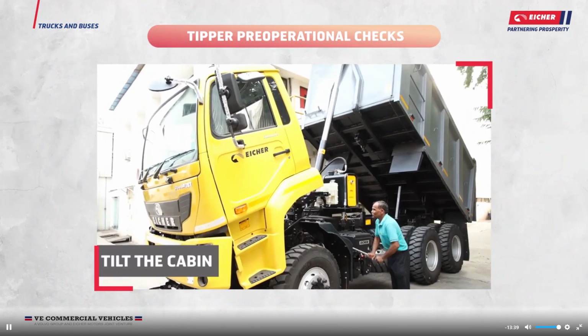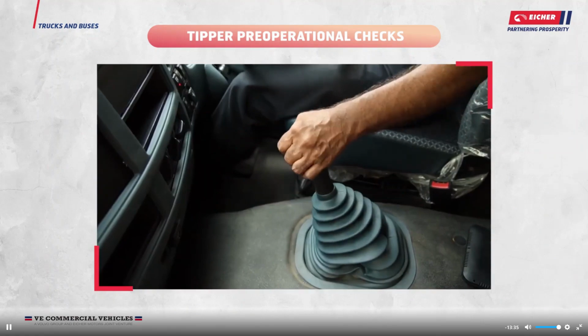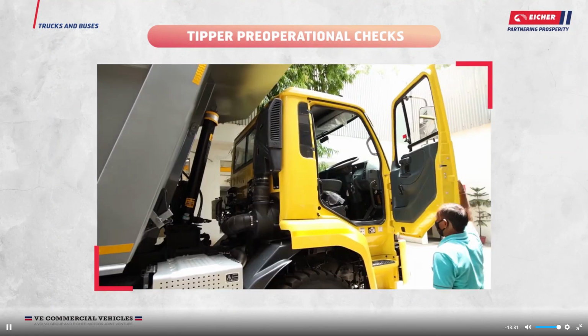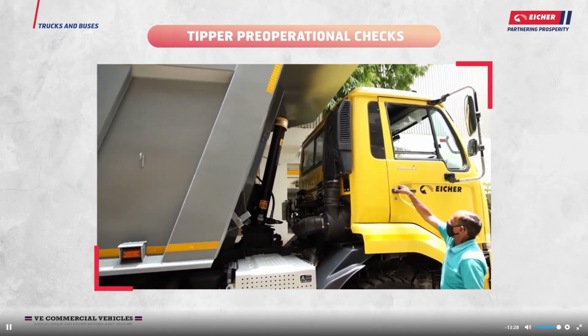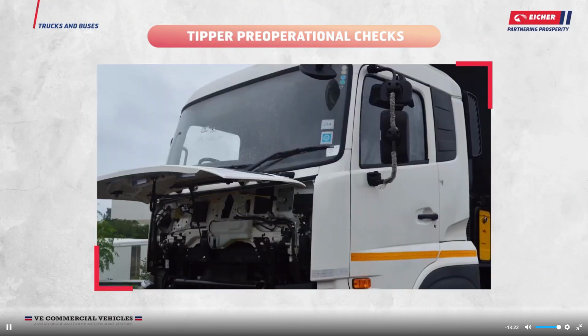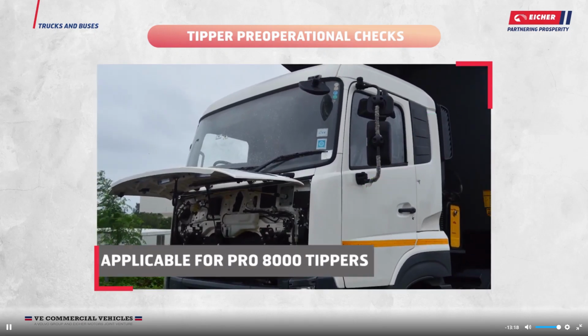Tilt the cabin to the end position and lock it. Ensure before tilting the cabin, the gear shift lever is in neutral position and check if the doors are properly closed. Check no loose items are present in the cabin while tilting. Open front flap first before tilting the cabin. Applicable only for Pro 8000 tippers.